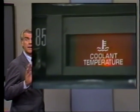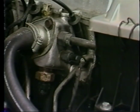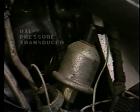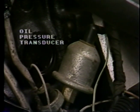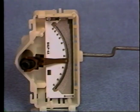Temperature lamp circuits work similarly, except the variable they monitor is coolant temperature, which can again be quickly checked by grounding and ungrounding the wire at the switch and checking the switch for continuity at the proper temperatures. More advanced systems use transducers to send more precise information to the driver via gauges. Transducers typically are variable resistors or thermistors which can change their electrical resistance depending upon the parameters being measured.